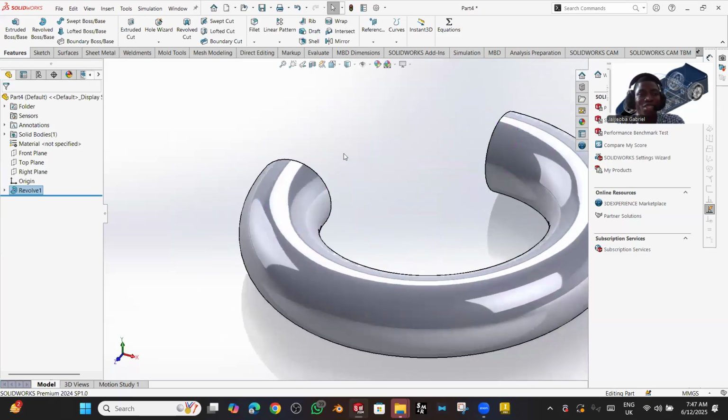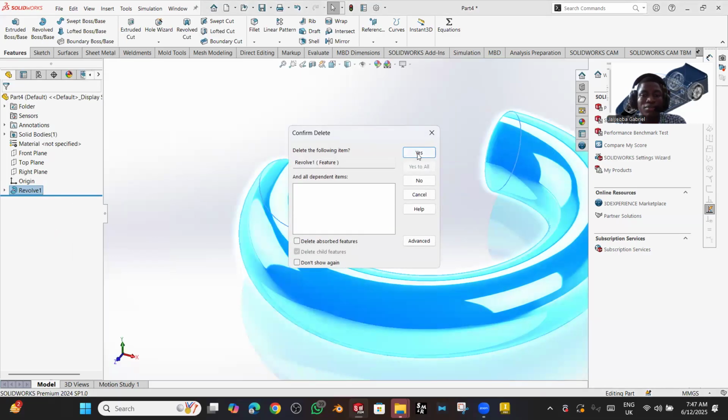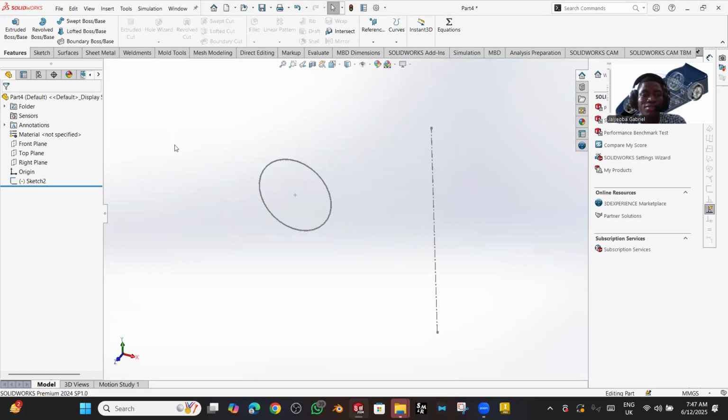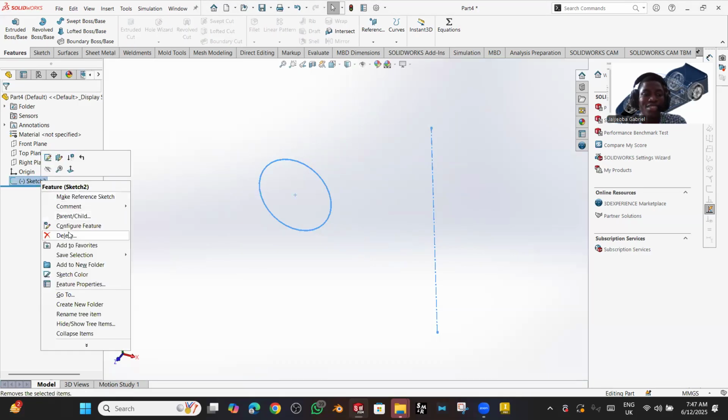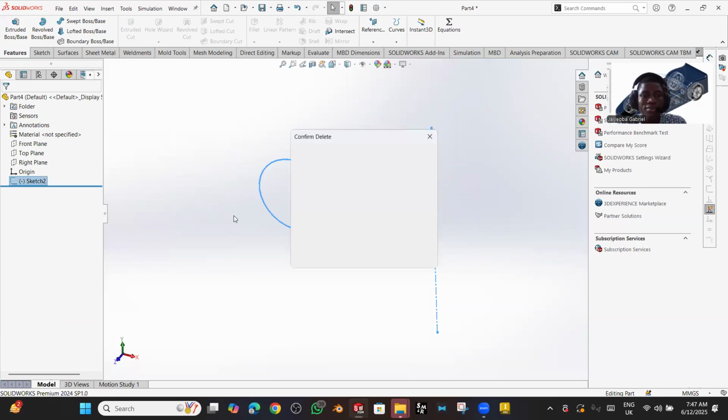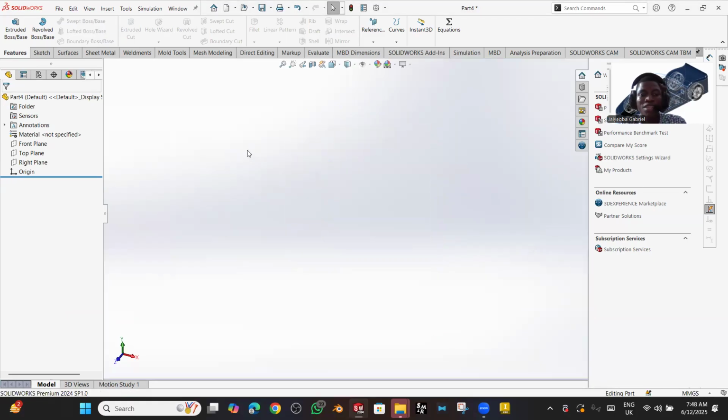Now, I still have some other things I want to show. So if I want to loft, yes, let me explain loft as well. How do I loft? Lofting is creating the transition between two sketches. So I have two sketches, whether parallel to each other or not. So let me select my plane.